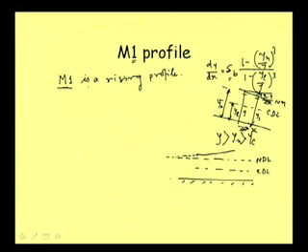We can call this the starting of the gradually varied flow profile, this section. From here suppose it is rising, but at the extreme upstream end, we are getting y equal to yn, the normal depth. That is bound to be, because it is coming down like that. Now, if this is the situation, let us see what will happen at the upstream end.